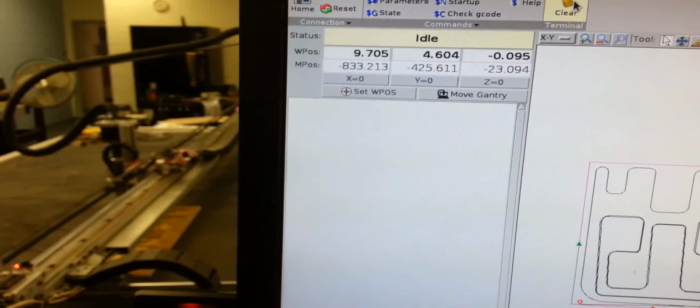So that's something that needs to be fixed, not by bCNC, but Grbl needs to accommodate G90.1 because that's the way my code is coming out of my CAM, and I haven't figured out how to do that yet, so I'm stuck with this until somebody helps me figure that out. But anyway, you can see that bCNC is having issues for some reason, and it's causing my machine here to freak out.